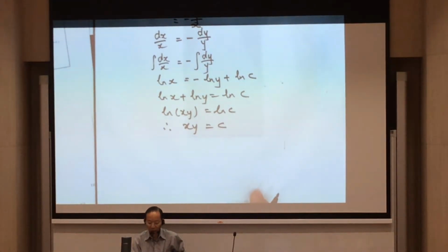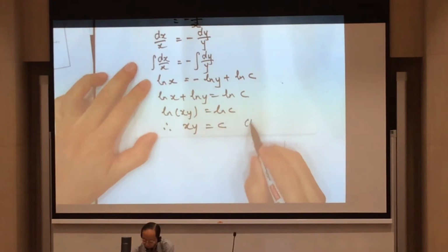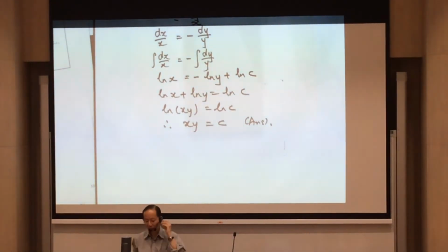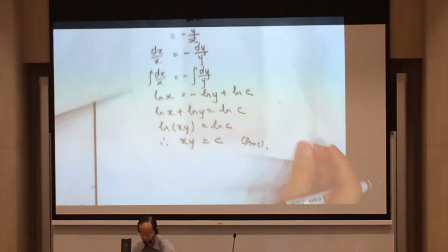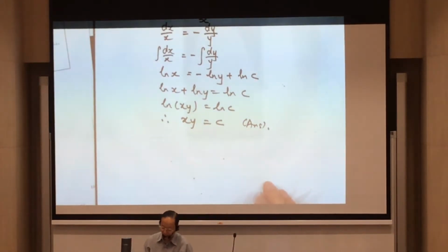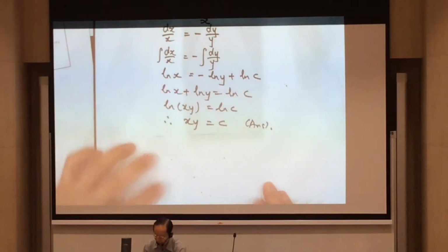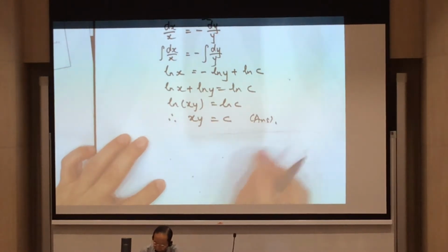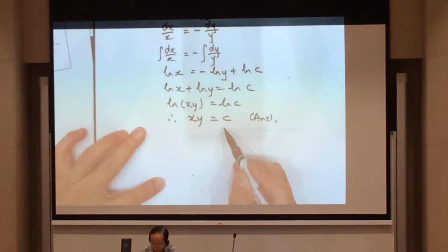Okay? So this is the equation of the streamline of the jet flow. xy equals c. So there's no time in there. Time doesn't go in there. Right? xy equals c. So how do we interpret this? How are you actually able to sketch this? Before we sketch, we will give some numbers. This will give different streamlines with different values of c.